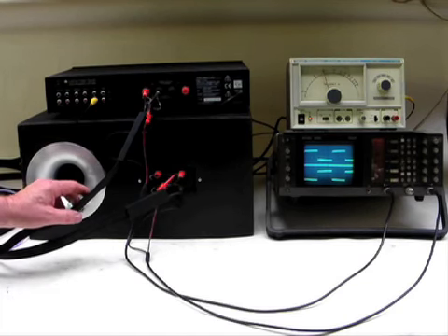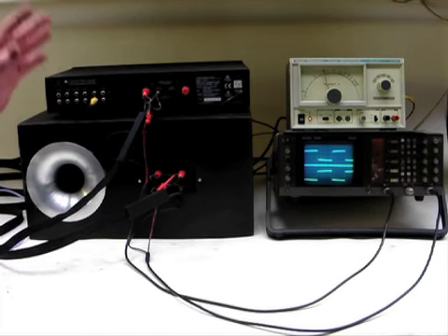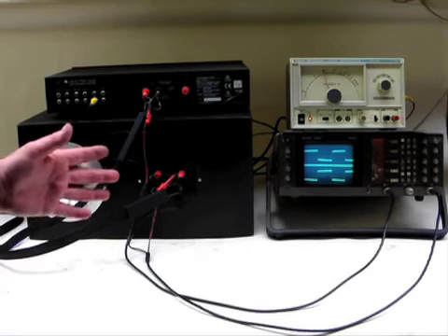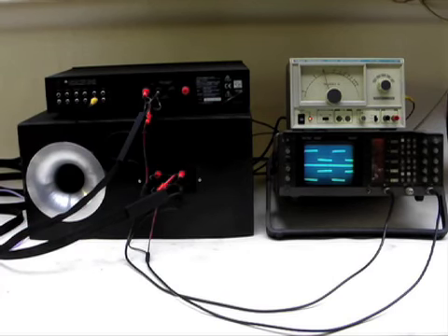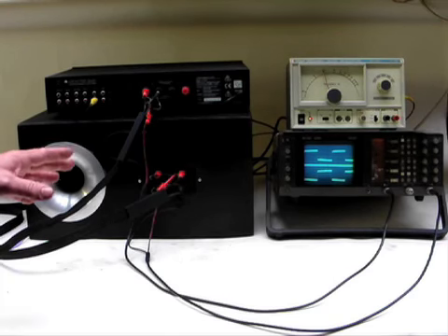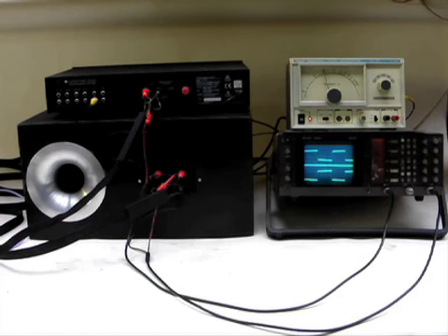And the reason for that is it's got high capacitance and very low inductance, so that the square root of the inductance divided by the capacitance works out to be about 8 ohms. And this proves that transmission line properties occur at audio frequencies, very often denied by people who don't really understand the difference between a long transmission line and a short transmission line.